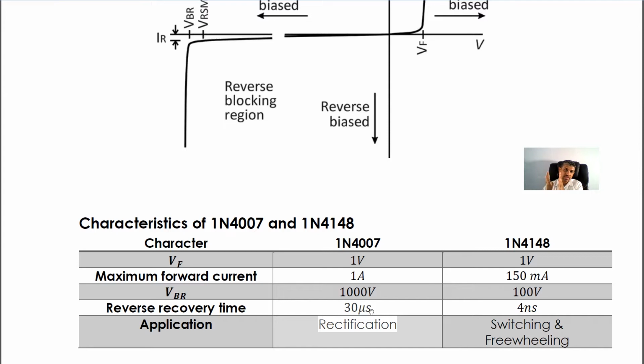You know, there's a layer at the PN junction. The junction has a special layer called the depletion layer. So when we increase the reverse bias voltage, the depletion layer will increase. When we apply the voltage in the other direction, gradually the depletion layer will vanish.